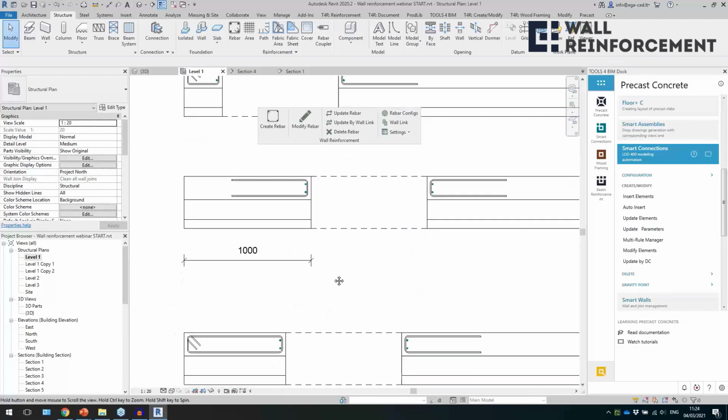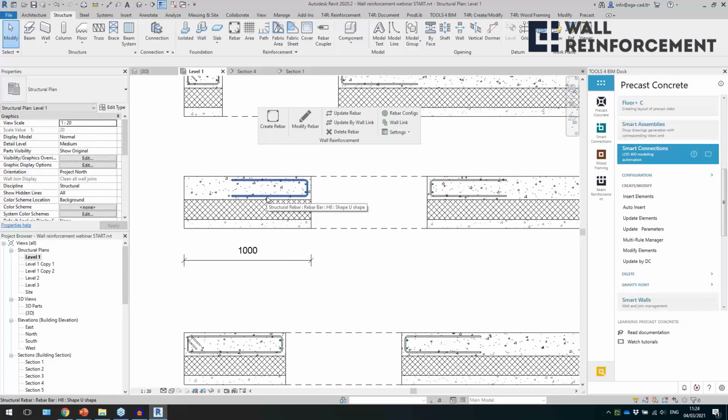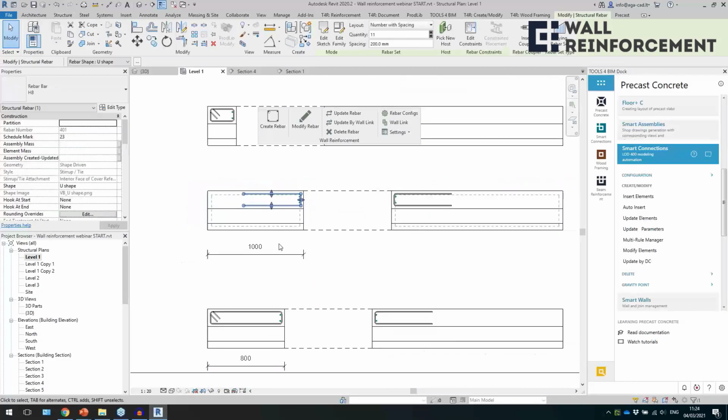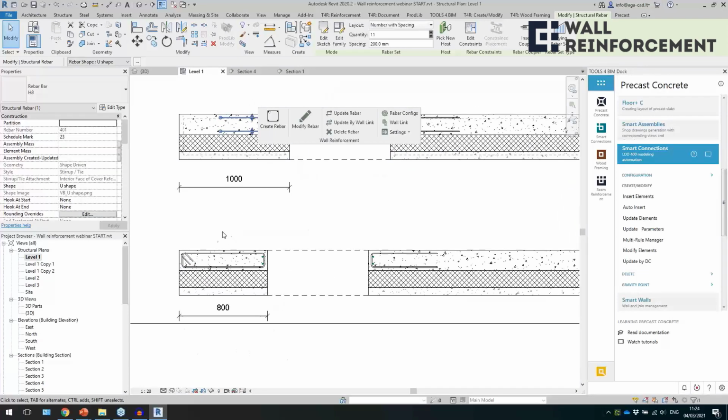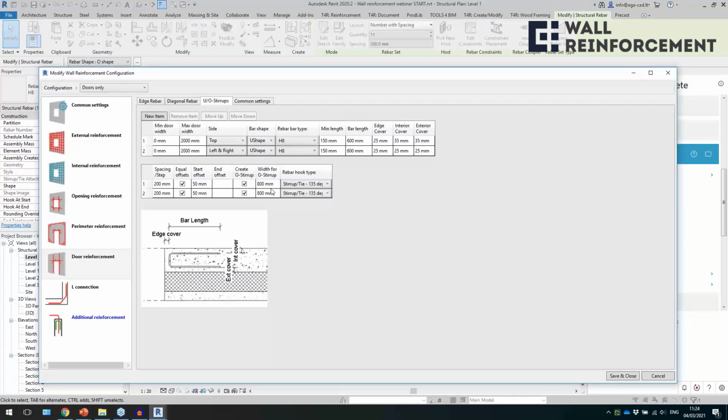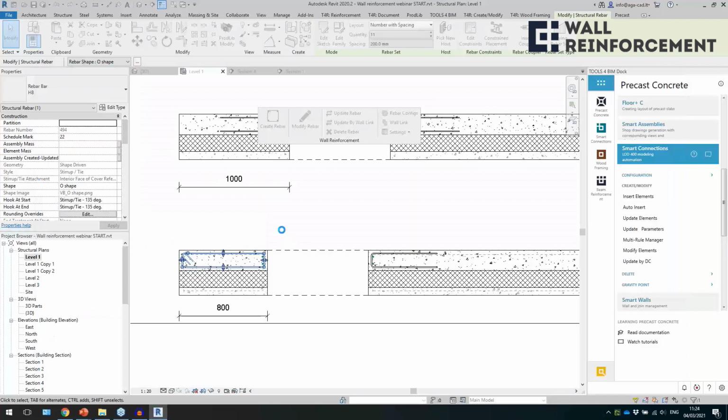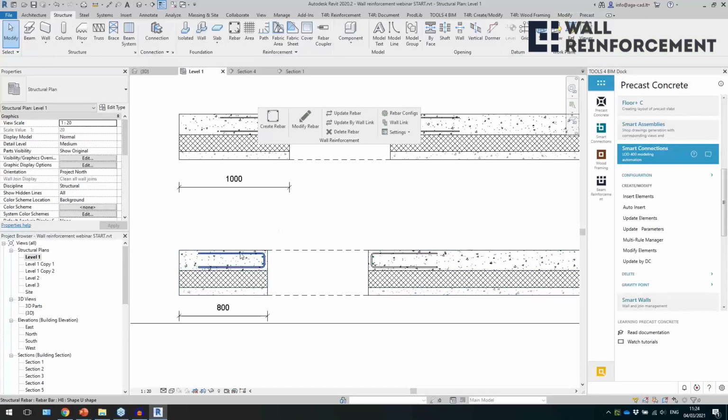also you have an option like, if I have an element here, right, and maybe there's still plenty of space for the U-bar, but maybe I actually want to have an O shape. So I have an option here: if the solid depth is smaller than that, the U-bar will be created, right?